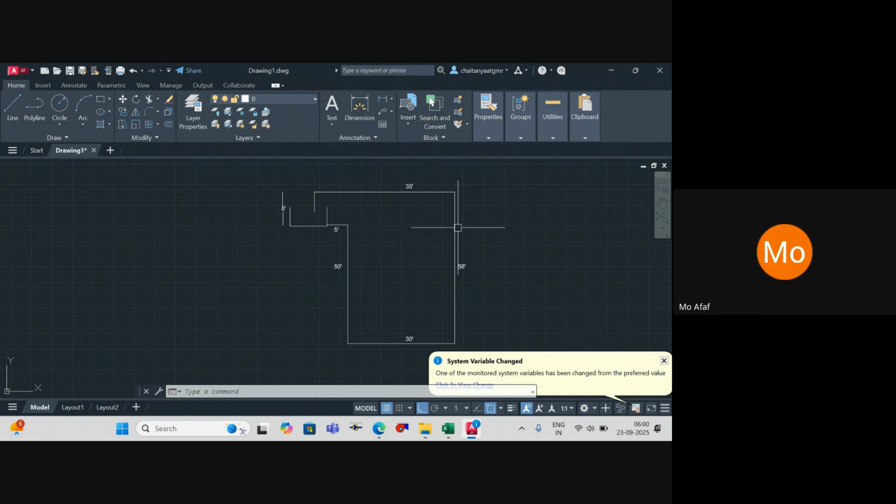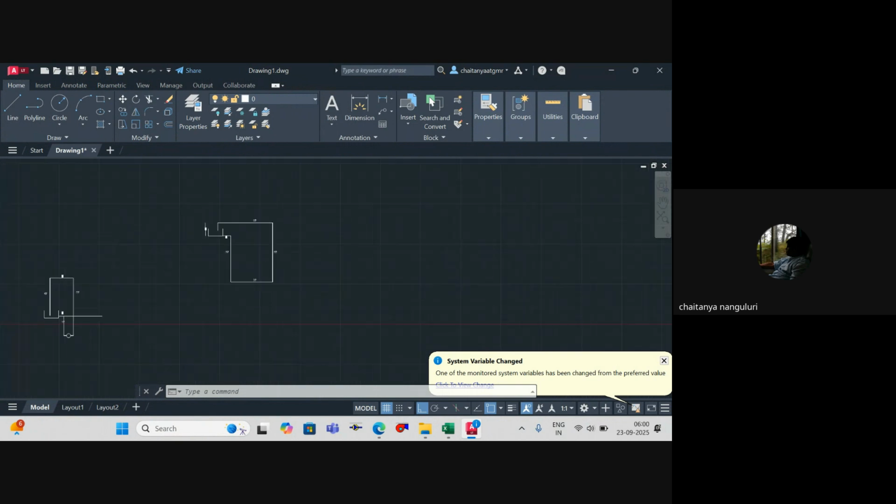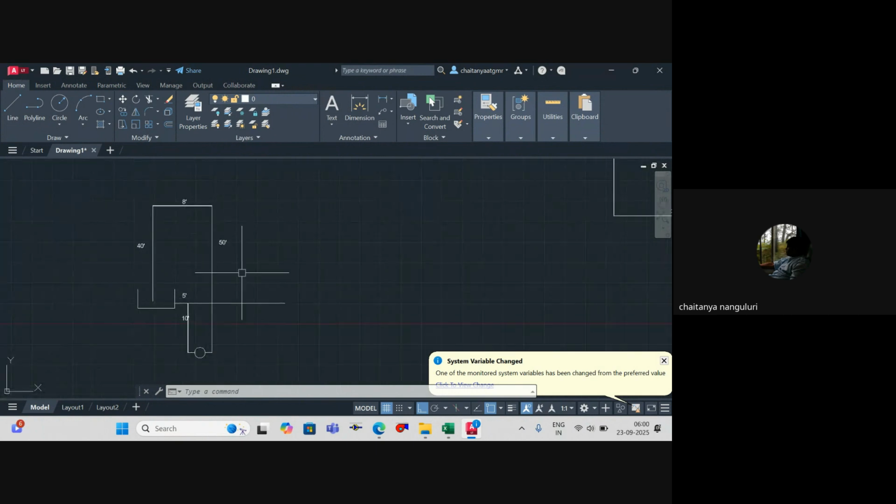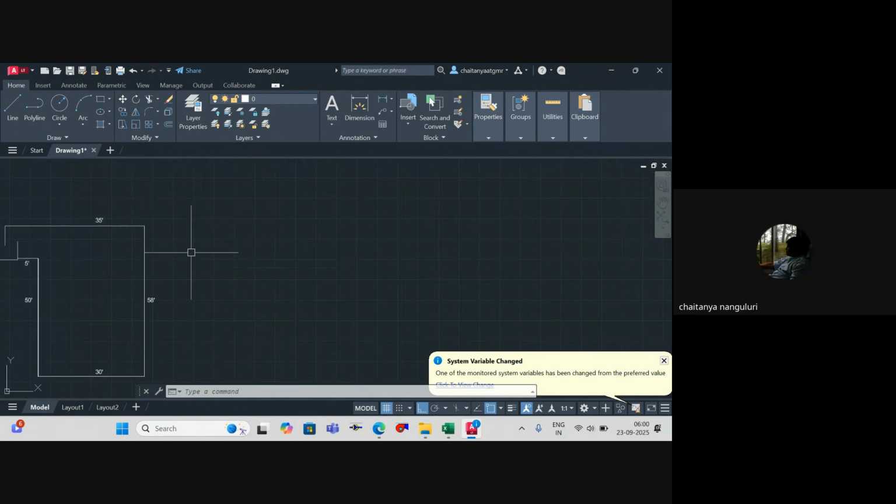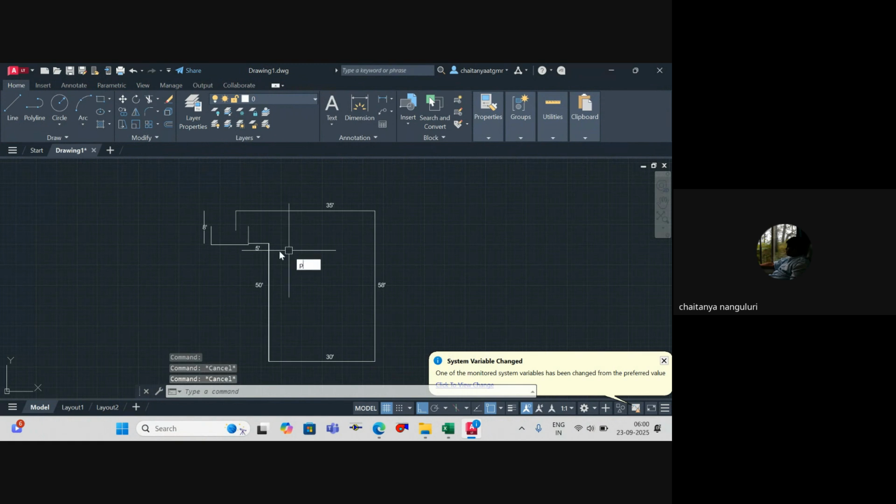So this example is for a cooling tower. That's the reason we always place the cooling tower above your chiller. If you have placed your cooling tower something like this, you will have a lot of losses. So the cooling tower will always be placed above the chillers for this simple reason. Only the height of your cooling tower will be your static head. Understood? Okay.